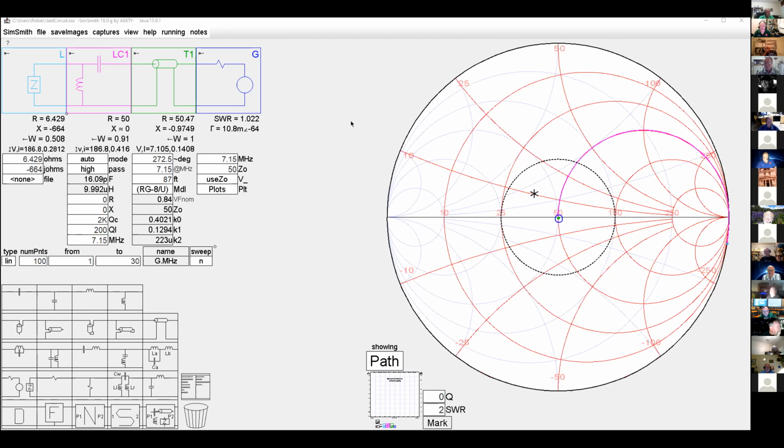No, those are great concerns. But here, I'd like to make this comment. I'm with you 100%. I think one of the best things any new ham could do would be to take EZNEC and go through those antenna models, those preliminary ones in the Get to Understand EZNEC section, and take a simple dipole and change its elevation, build it for a certain frequency, put it close to the ground, and raise it up. And each time you raise it a certain number of feet, look at its pattern and look at its impedance and all that stuff.